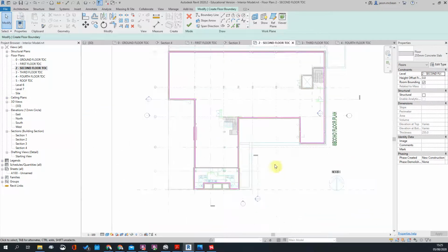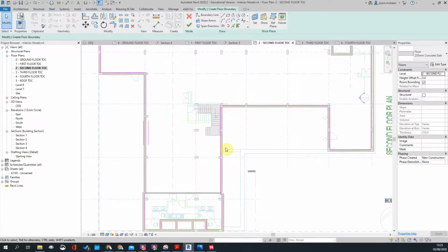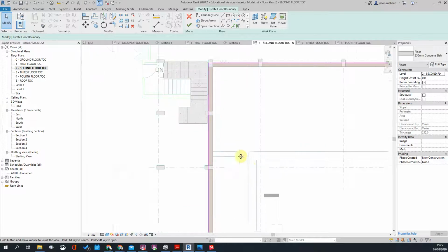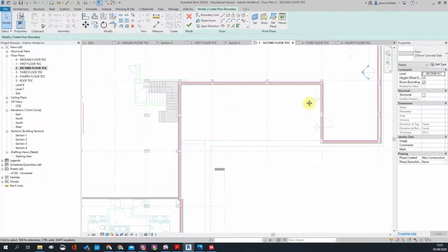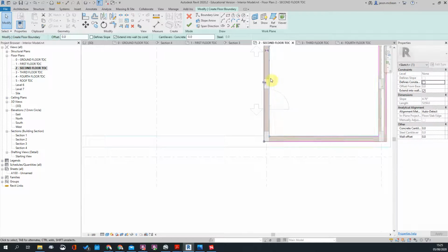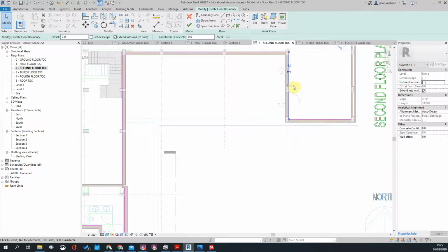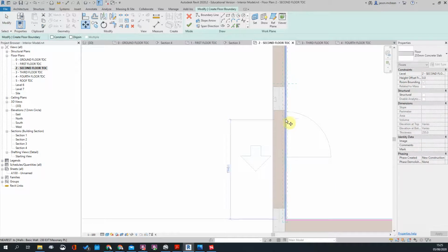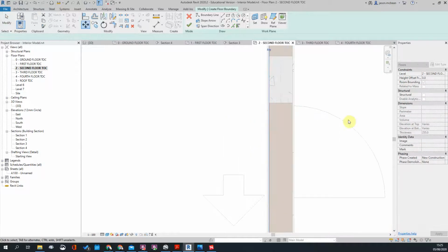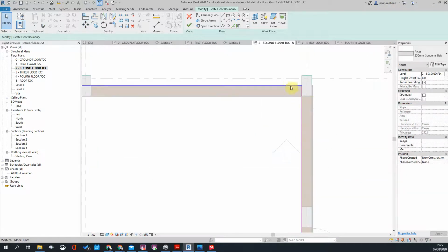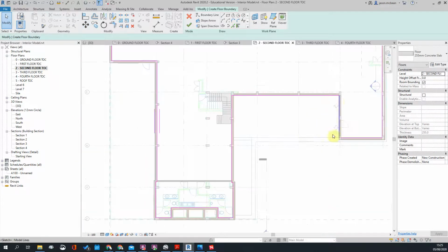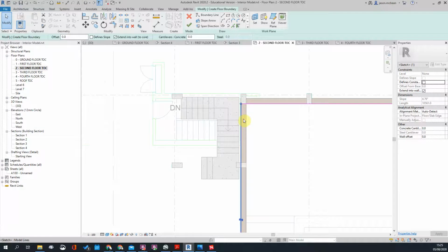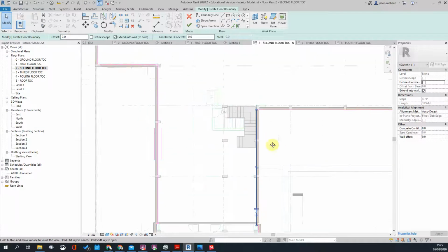Okay, now we're going to have, so that's one series of slabs. But now, my guess is you might find where the doors are, the line of this slab will move from there to there, because we're going to have two slabs and there will be a level drop because you don't want water going back into your building, for example.